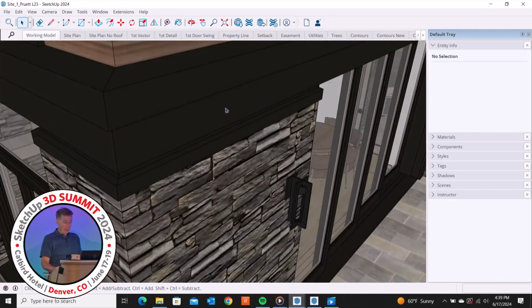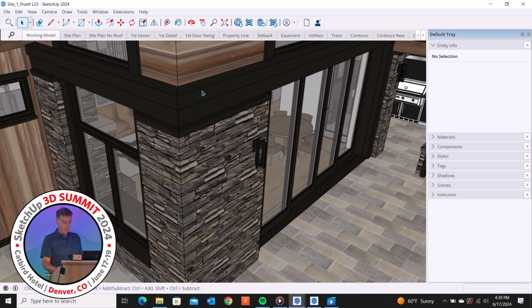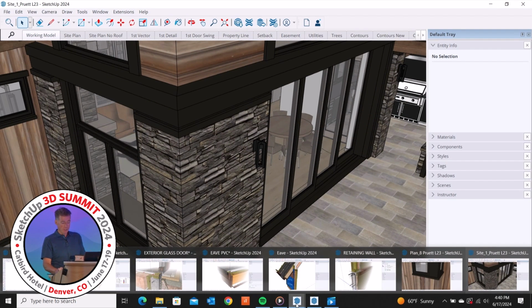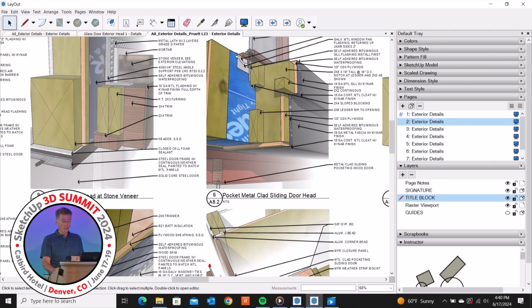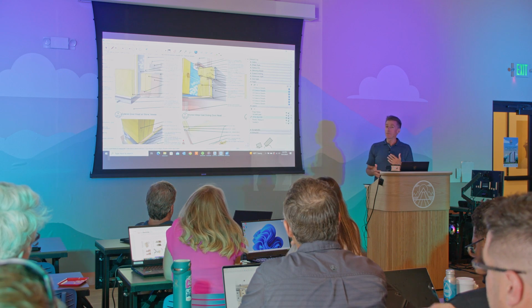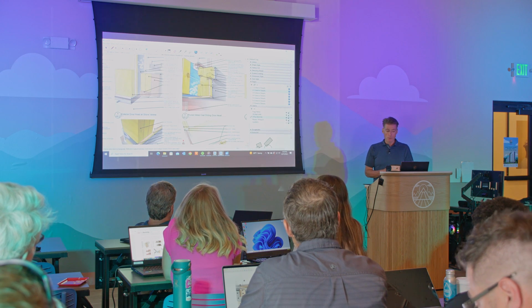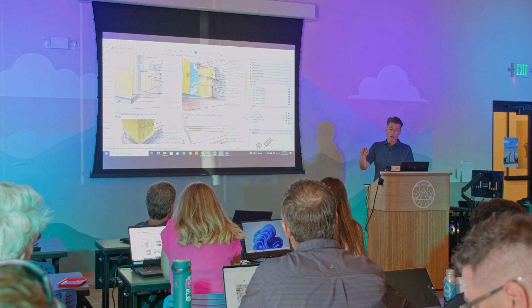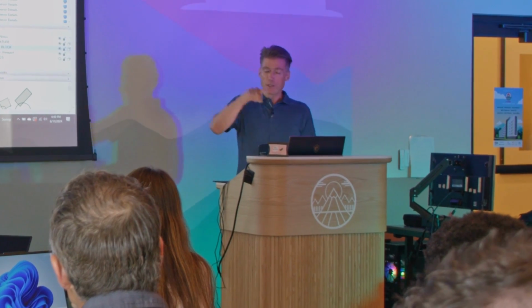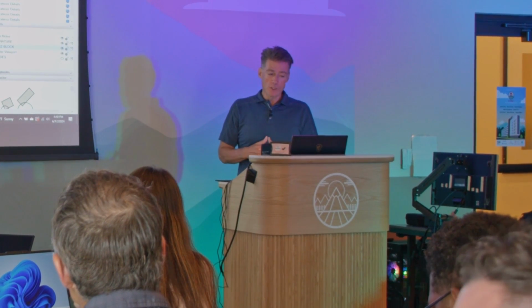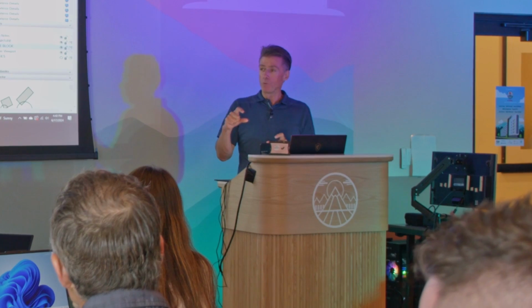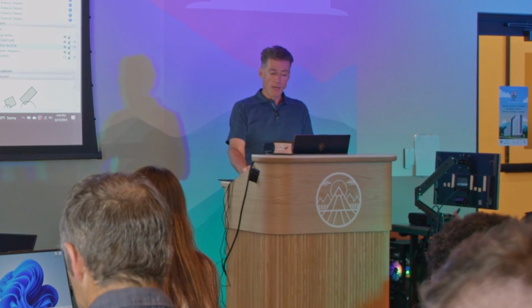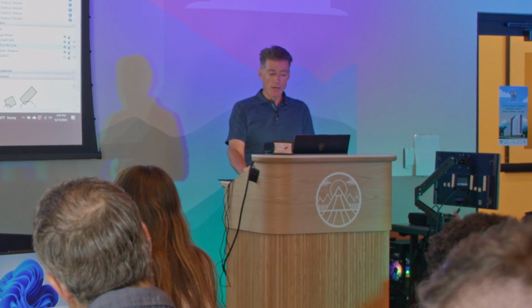I capture what that profile edge is from the model, and then I'll bring it into SketchUp, or into the detail piece, to match exactly what that profile is, and then I think about how I'm going to build that out. In this case, I just made these individual blocks that are cut to the shape. We put those at 16 on center, and then solid where we need all the nailing. So we have it up here, so it'll notch up and around there.